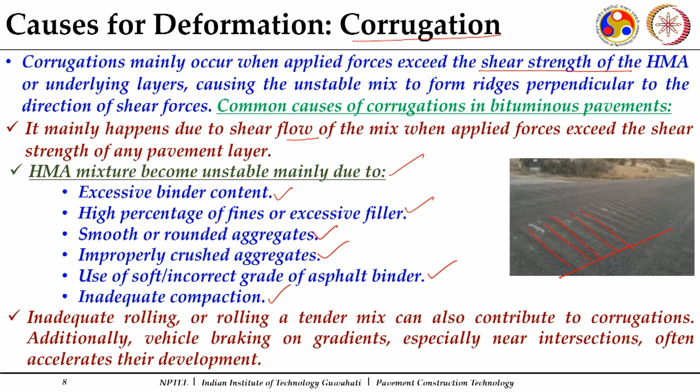So if these layers are not compacted, their density is less, and their strength is less. So when traffic comes over it, you can experience this kind of shear failure.